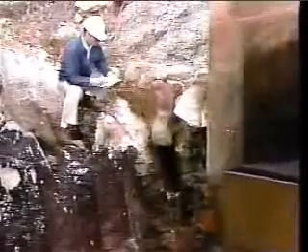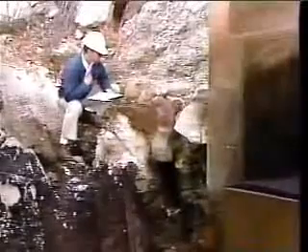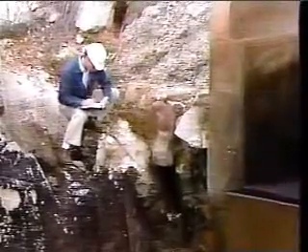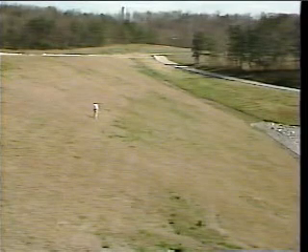In addition to the groins, remember that conveyance structures through the embankment are especially prone to seepage. This is what seepage adjacent to a water conveyance structure looks like. If you see seepage at any point such as this, consider it a serious condition. Let's look at another visual cue of seepage.